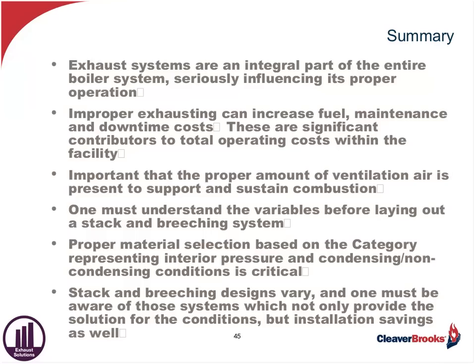For instance, with Cleaver-Brooks and our fire tube boilers, depending upon the model, we can withstand plus or minus anywhere from 1/4 inch to 1/2 inch of variance in stack pressure without adversely affecting the burner and combustion. There might be other people out there that say, look, I've got to have 0, and that's it. 0 at the vent stub. If you give me any variation, I'm going to have problems. Well, that's fine. Then we just design around it.